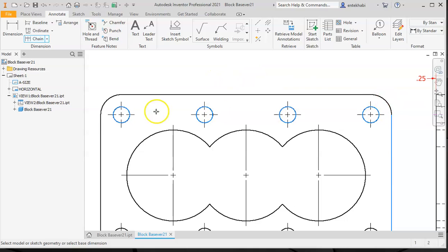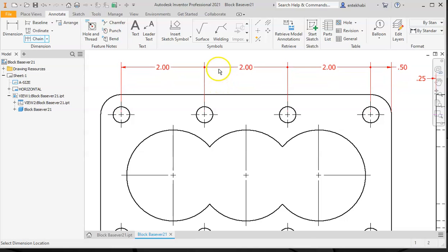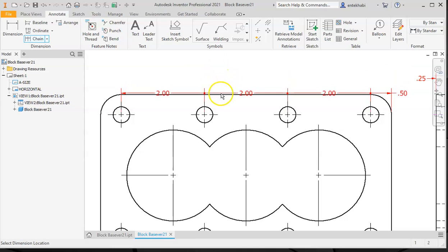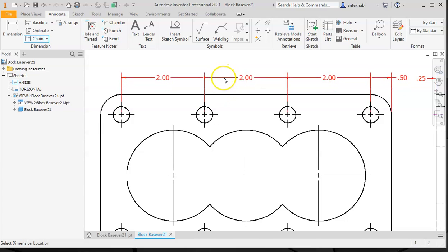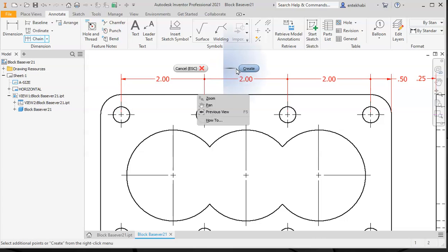Okay, after your selections, right click and continue. And now it's asking where, how far. So this is critical when you're selecting this point. I see some of you are getting too close. Try to do ½ inch, that guideline that we established in the beginning of the dimensioning section. So click on approximately ½ inch. After that, right click and say create. You need to do this last step, otherwise you would cancel. So make sure you right click and create.